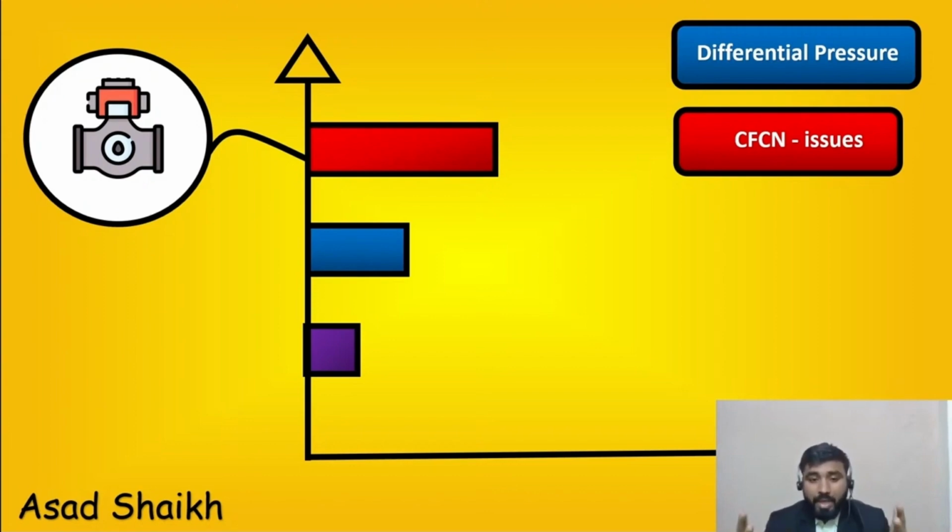If you see a butterfly valve, in terms of its construction, it's basically a vane which is rotating. Now imagine, especially at 60, 70, 80 degrees, maintaining its state at a very high DP, let's imagine 100 bar of DP. It's too difficult; it will start to vibrate. You have certain valves which have come in the market, called triple offset butterfly valves, but still it is very tricky to maintain that kind of position at such high differential pressures.